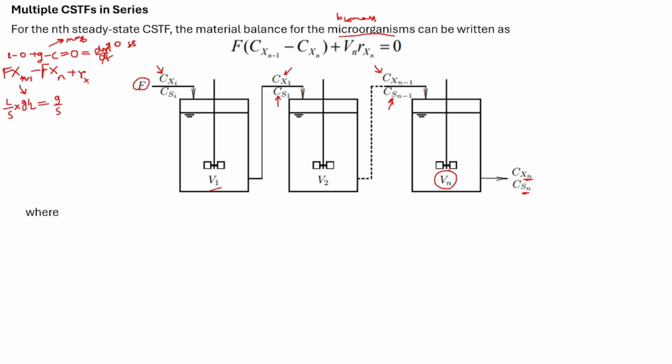Now what is the unit of this rate? Its unit stands at grams per liter second. Now we have to make this unit in grams per second. So what do we have to do? We have to multiply it with the volume. If we multiply it by liter, that means the volume, we get this unit. So we multiply it by the volume of the reactor. So this is the generation, and we consider there is no consumption of biomass, so it is 0.